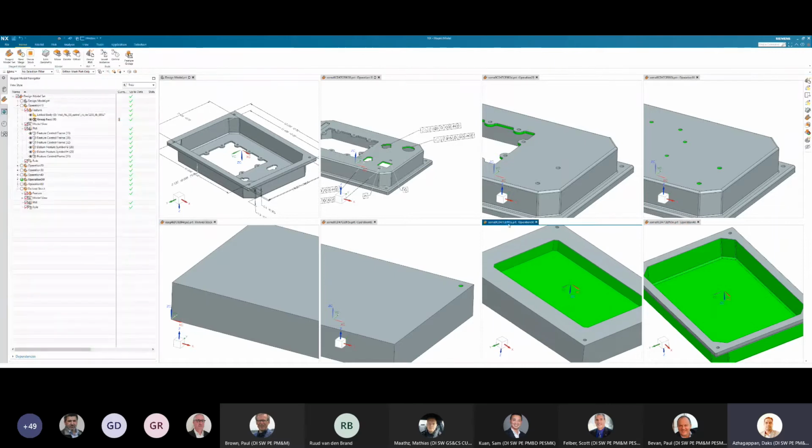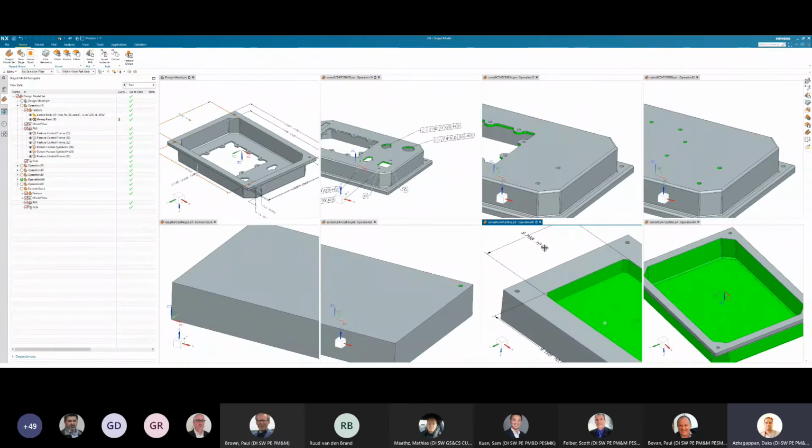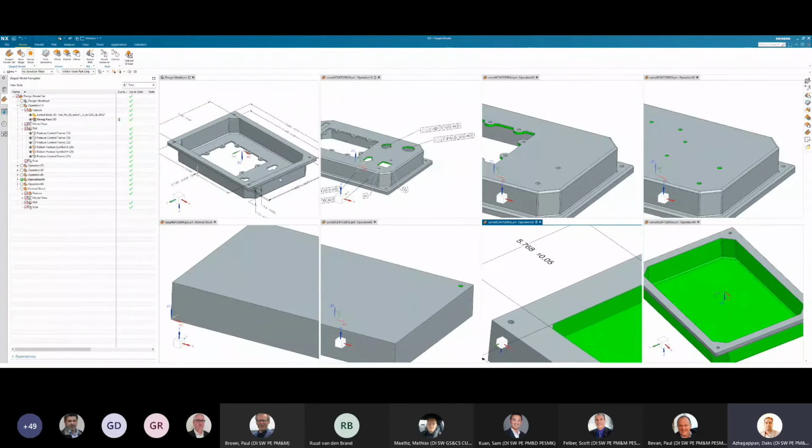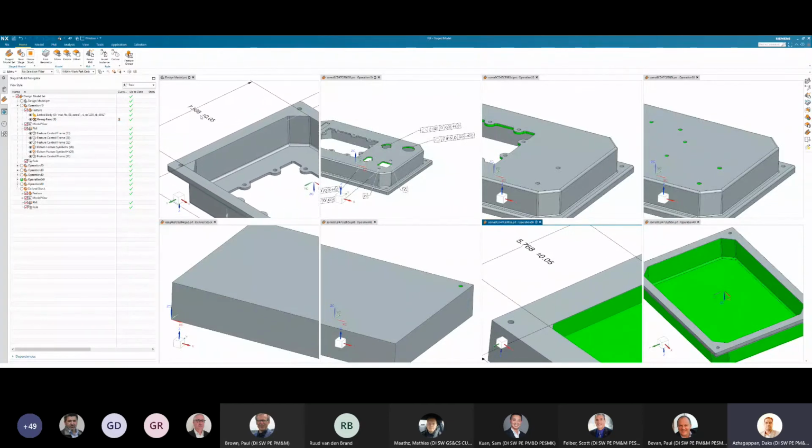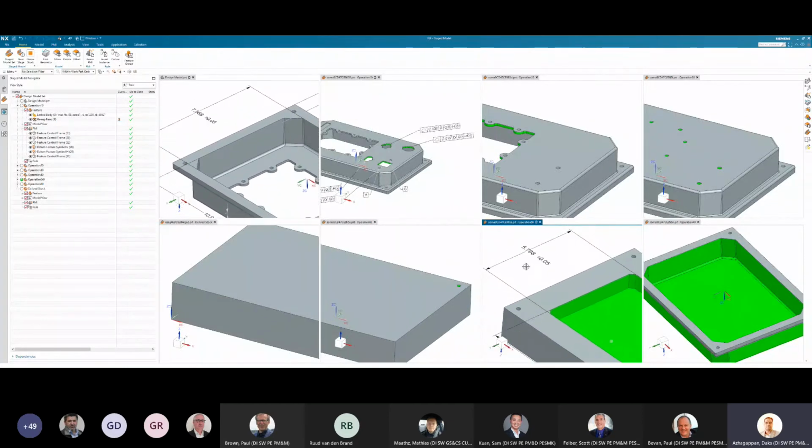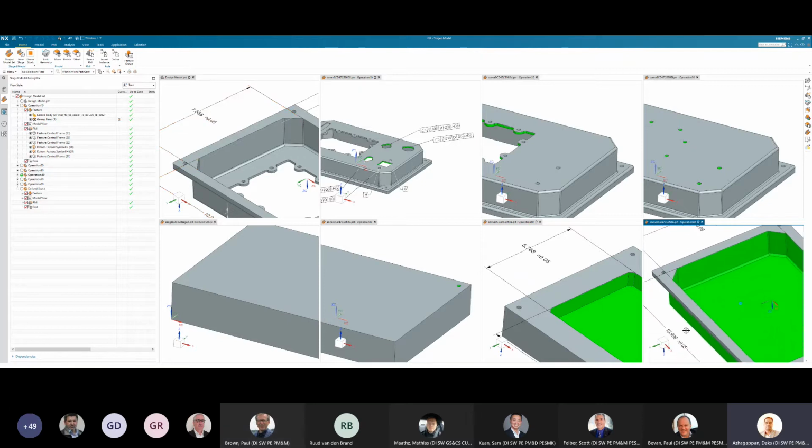So I'm going to come back into my operation 50, and I'm going to be using the reuse PMI. I need this PMI, I need this PMI here. You can also see that these sizes are automatically adjusted. The final shape is 7.568, and then here you can see the 5.768. If I go into operation 40, I want to reuse those PMI, and I'm going to select this one. You can see here, this is where I'm going to be achieving the final shape with the tolerance.